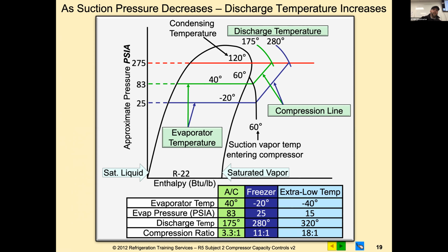We're getting lower capacities on the lower temperature. Yeah, we are. And refrigerant wants to continue to keep absorbing heat energy. It's going to continue to do that until we start to desuperheat under pressure, until we start to cool it. Then it'll try to give off that heat instead of absorbing it. That doesn't happen until it hits the condenser and begins to desuperheat.